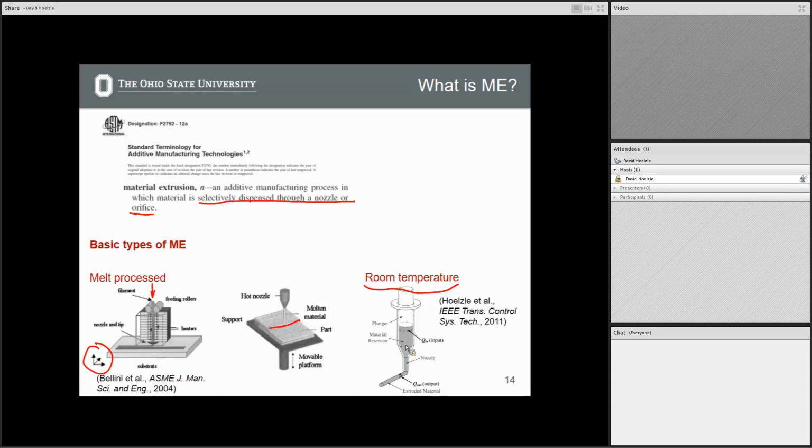But what you're doing is you're using materials that have certain interesting viscoelastic properties, that when they're not under shear stress, they behave like a solid, and they have a really thick consistency. And then when they are under shear stress, which is when they're being extruded out of the nozzle, they act more like a liquid. So you get the same idea of going from solid-like to liquid to solid-like, just as you would get with these melt process materials, but purely in the liquid phase. It's always a liquid. It just depends on the viscosity, how it behaves in that certain shear regime.